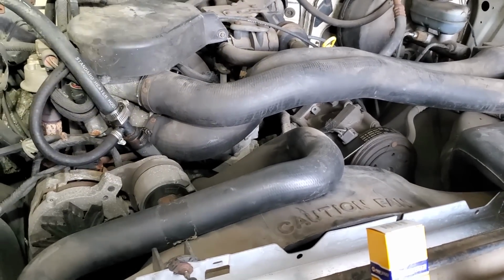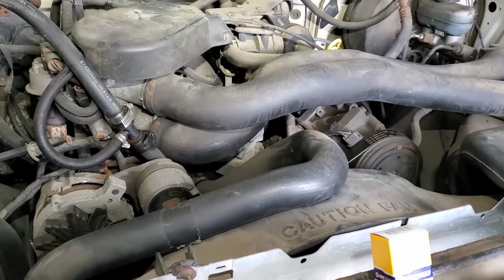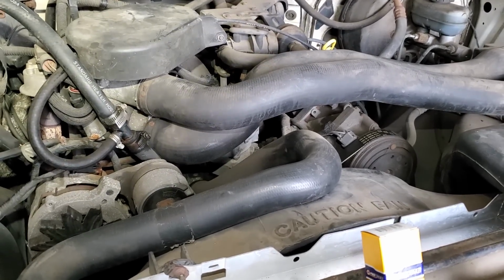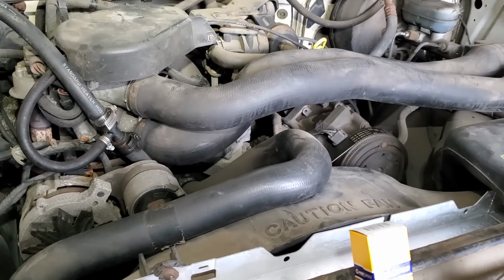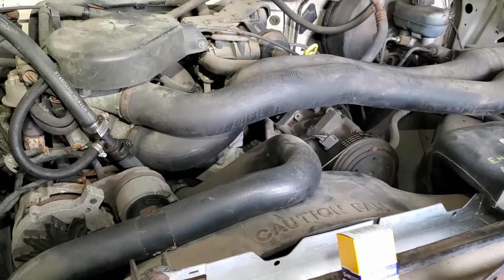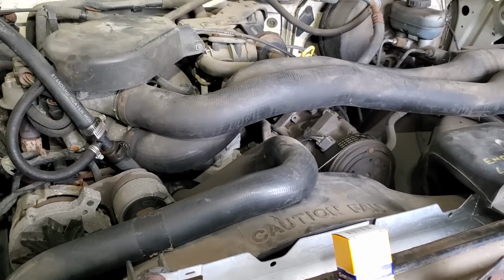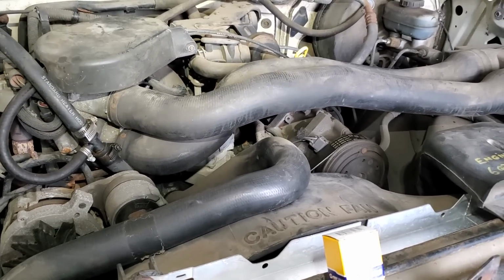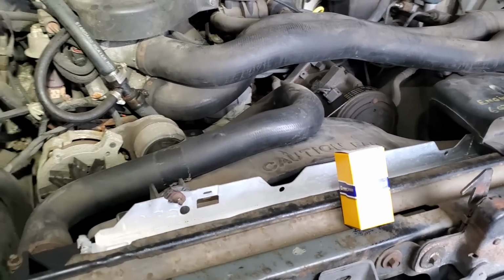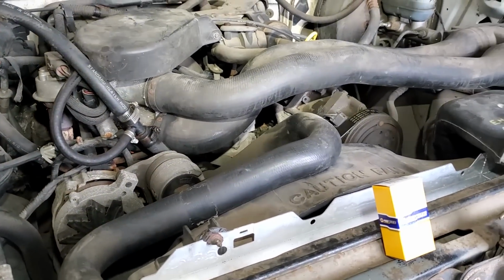And one of the main things with California emissions was carbon monoxide reduction when the engine was cold. So these vehicles, basically starting in about 1988, went to a 4-wire heated O2 sensor. And these go into closed loop as soon as the voltage on the O2 sensor comes up above about 0.5 volt. They'll start to feed back. I'll show you the 4-wire O2 sensor. That was sort of the most common.